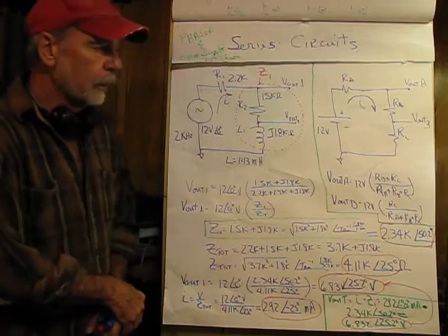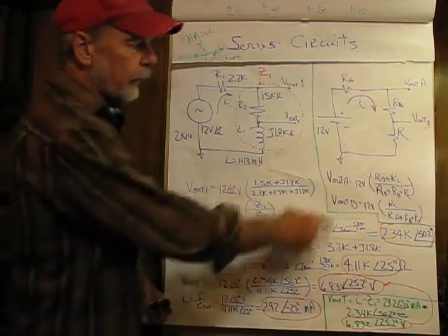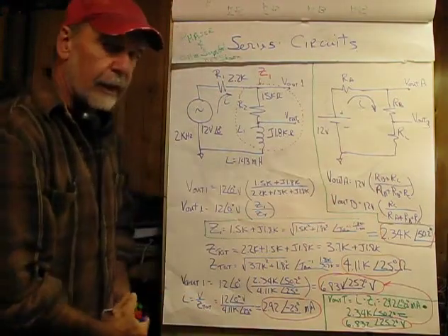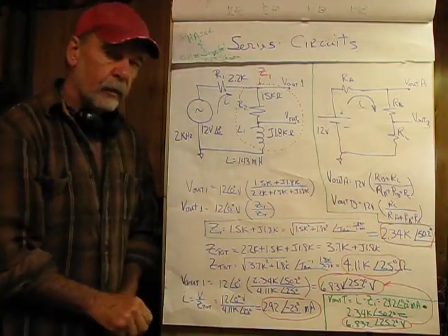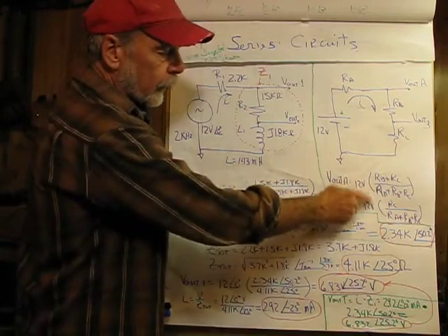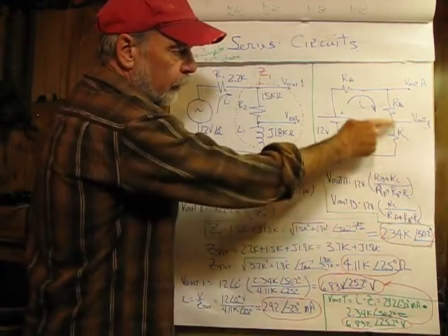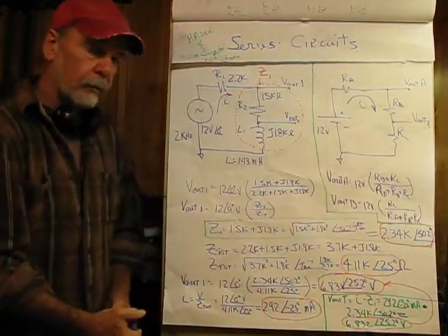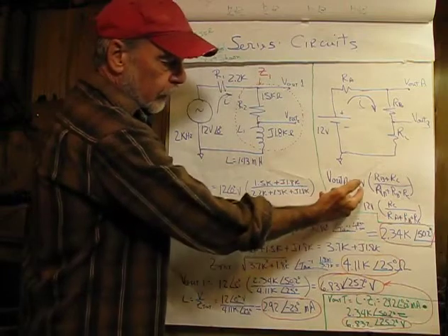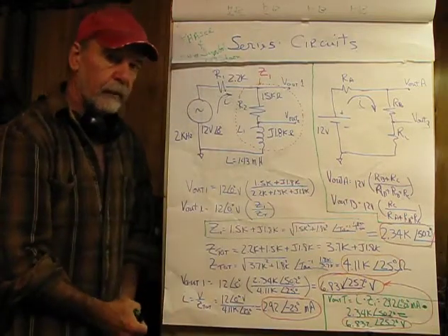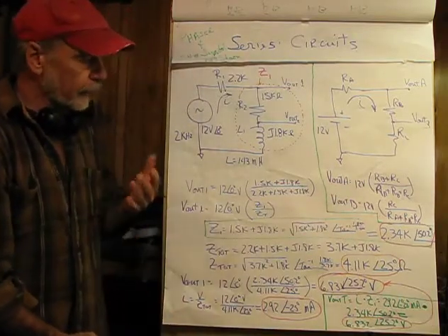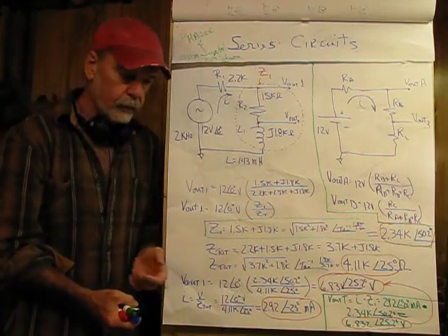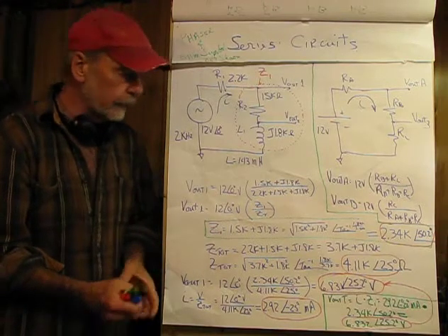Because this is a pretty busy diagram. Start out in DC circuits, and this is where we'll begin. We want the voltage VA out with respect to ground, and we would set that up in voltage divider, having in the numerator RB plus RC, and in the denominator R total, and that ratio is multiplied by the source voltage, which is 12 volts. So we're going to use that same technique in AC, except we have to deal with phase angles, which we didn't in DC, which makes it somewhat more complicated.